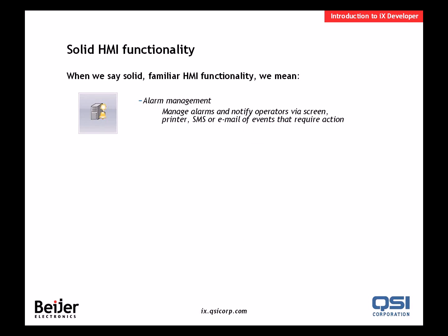Alarms is a crucial part of any HMI application, and the alarm management in iX is very powerful. You can have an alarm trigger an external action. You can change screen, backup data. We have a fully customized alarm viewer that you can add to your screens.